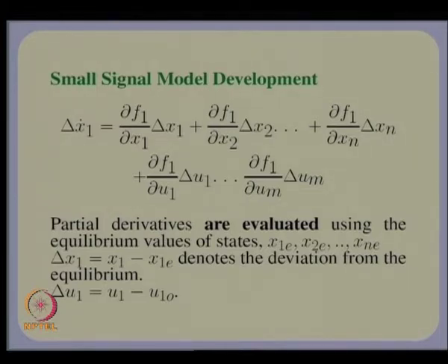You may say that, well, this looks different from that. No, actually, if you take out the partial derivatives of the function psi d iq minus psi q id, and plug in the equilibrium values, you are going to get exactly the same linear model as we got some time back. So, in fact, this is a more general and direct representation of what we will get if we apply this linearization with delta x and delta u very small.